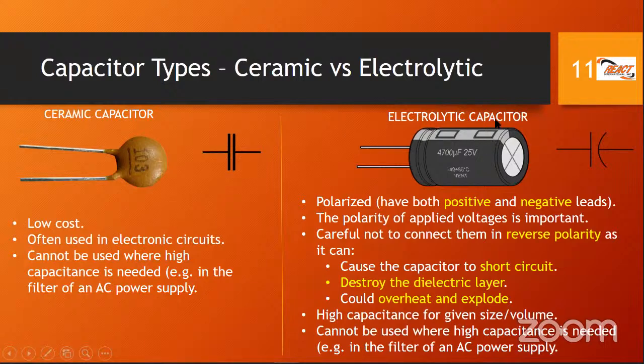But we also have another type of capacitor that we had seen before, the electrolytic capacitor. Now, the thing about the electrolytic capacitor is that it's polarized. One leg is positive and the other is negative, or you have plus and minus on the two legs. Notice in the ceramic capacitor, we did not say that. It really doesn't matter for a ceramic capacitor how you put it into the circuit. You could put it in straight, you could put it in reverse, it doesn't matter. There's no positive or minus in the ceramic capacitors.